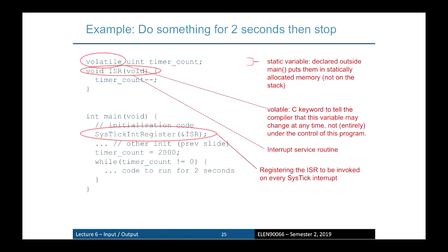So that means if you're writing an interrupt for this M3 ARM chip here, it's as simple as using their built-in functions and then writing your own interrupt service routine and your own code. So what does all this do here? The whole goal is let's do something for 2 seconds. So we're going to set up a timer for a certain value, let it tick down, and then after 2 seconds, hopefully, it causes an interrupt or does something, right?